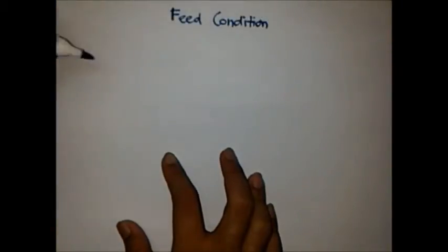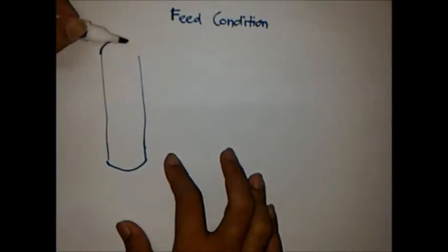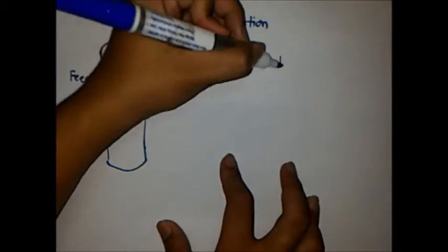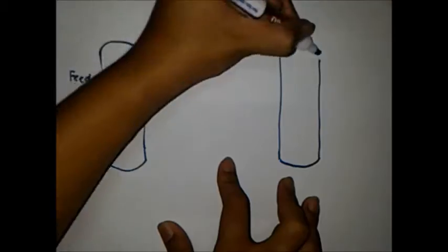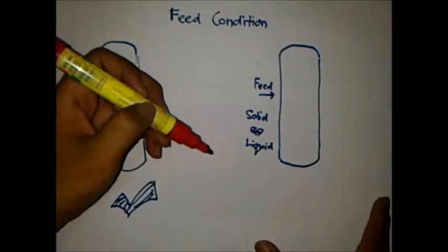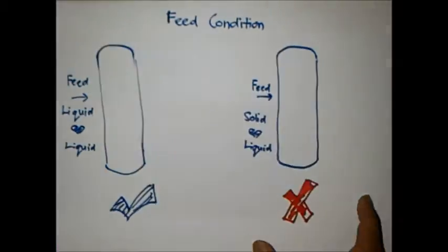For a successful distillation process to occur, a good distillation column must be used, since a good distillation process is characterized by the performance of the distillation column. There are several factors that might affect the performance of the distillation column. The first one is feed conditions. The state of the feed mixture and feed composition affects the operating lines, thus affecting the number of stages required. The column may no longer be able to handle the separation if deviation is excessive.